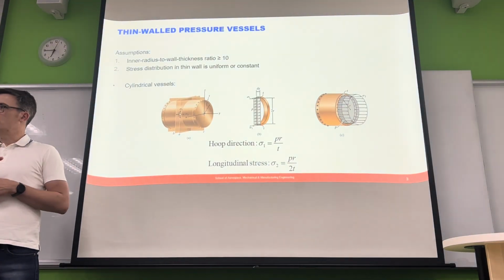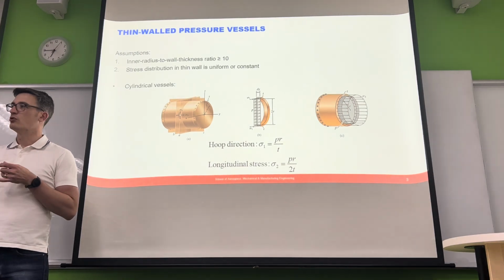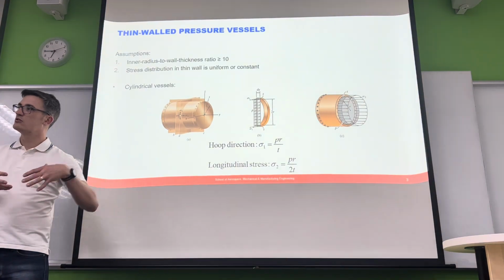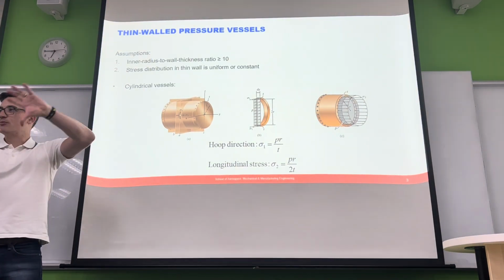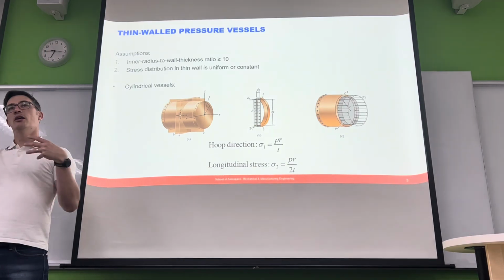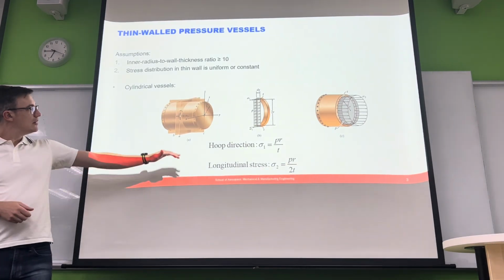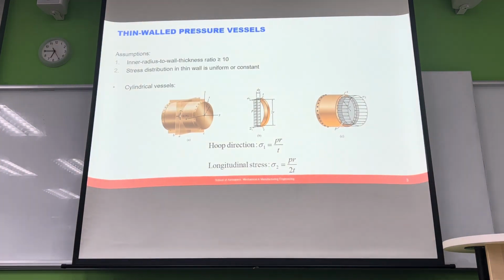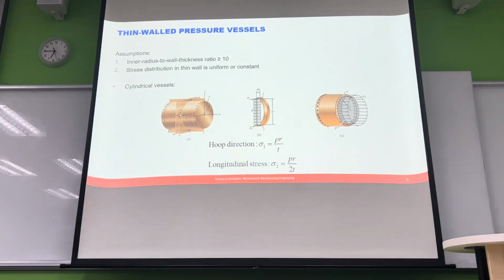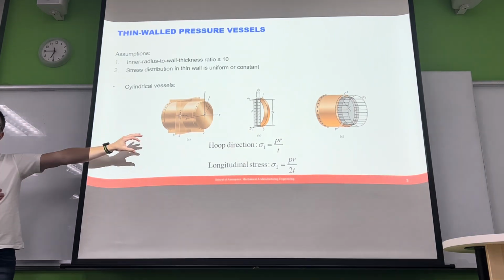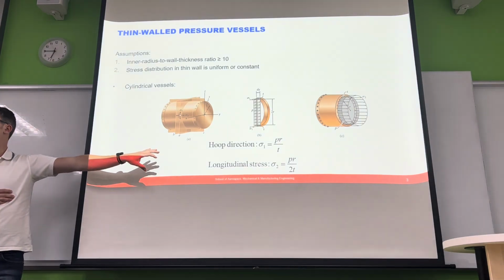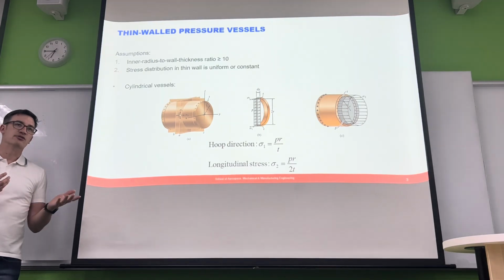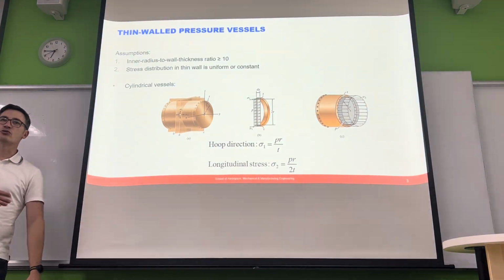I teach a course back in Melbourne called Finite Element Analysis, which is a more advanced structural course using computational methods to look at stress states. So we can look at any arbitrary shape and put any arbitrary loading on it and represent the stress state in the system. But still, I always come back to recommending to my students that they think about the stress loading in terms of these more simplified models. So things like your continuum mechanics, MY over I, force over area, your hoop stress, your longitudinal stress, and all these other ones.